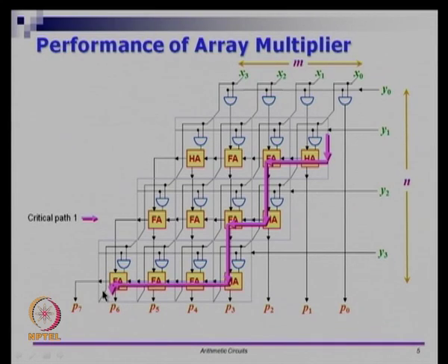So, this is one of the critical paths, and there is another path which is also quite long. What happens in this one is, you go down on this and there is a carry that is coming from this stage itself, right. This stage is the addition that you are doing for the first partial product with the second partial product. That adder itself may have a delay, and once that settles down, it will then go down like a staircase.